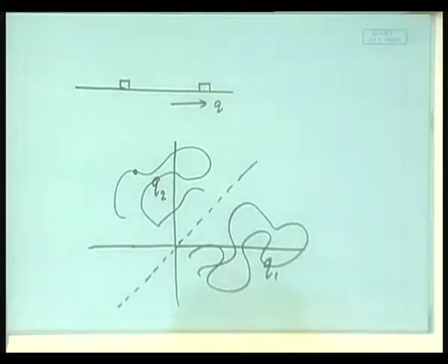Fine. So, the non-holonomic constraints, as you can see, do not reduce the system dimension, holonomic constraints do, and fortunately most of the engineering systems have some kind of holonomic constraints. So, it will be more important for us to utilize the advantages of holonomic constraints. So, let us pay some more attention to that.